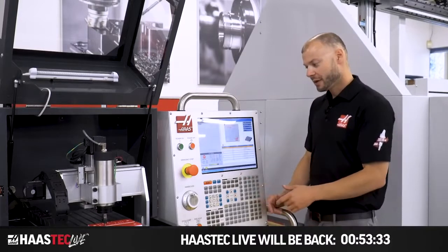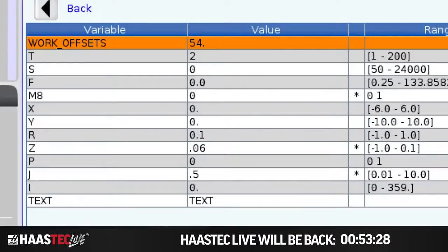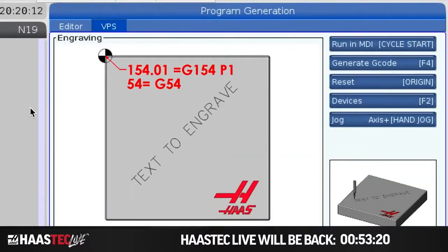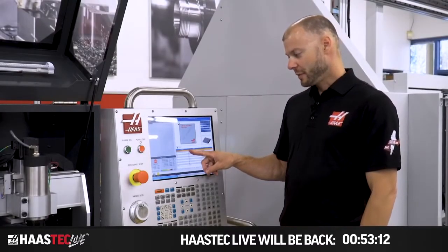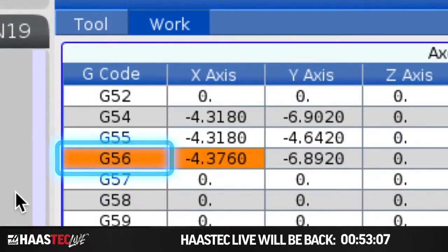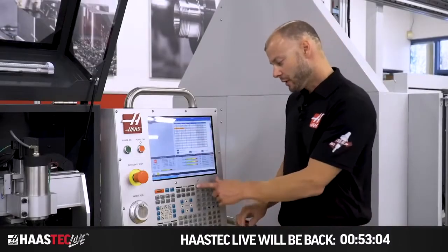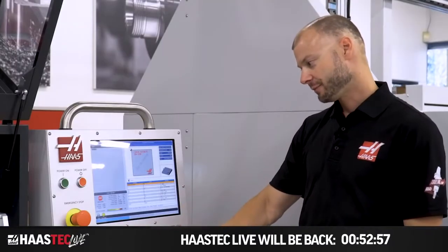So let's see what it takes to operate one of the VPS templates. These are all composed in a very similar manner, and basically you're just answering questions from top to bottom. We have useful pictures that help determine what inputs we're looking for, and we have some help text down here. So the first thing it's asking for is our work offset. By default it chooses G54, but if you remember, I set G56. So I'm going to enter 56 and enter button, and now we're using offset G56.